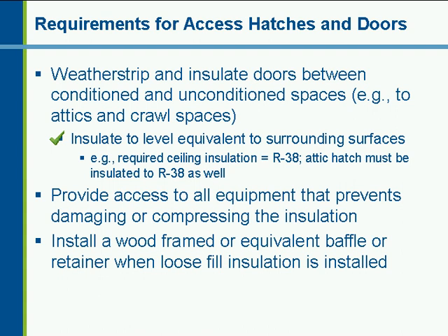There's also a requirement that you give access to any equipment that's up there without the repair person having to step on the insulation. You can't just blow insulation all around the air handler. You must build a platform up to the air handler that's over the insulation, for example.